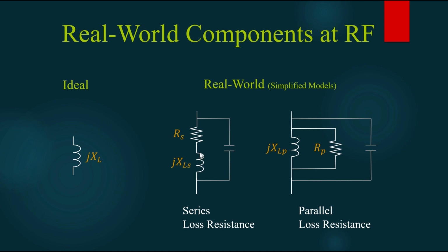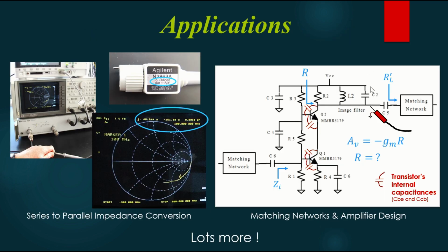And for a lot of circuits, like this one, the inductor is in parallel with a capacitor. It's forming a parallel RLC circuit. And so it unnecessarily complicates things if we put a series resistor right here. We'd much prefer if the inductor had a parallel resistance, because then we could combine it with, for example, R2.